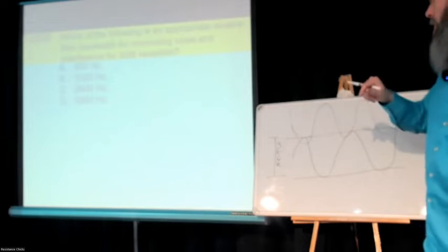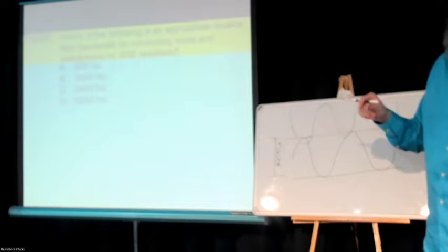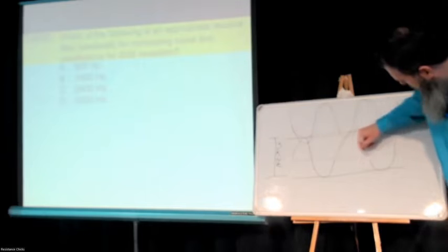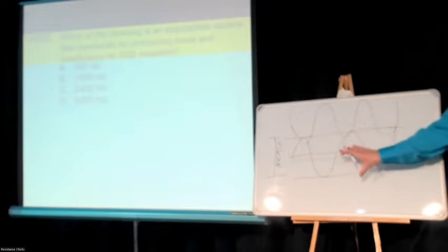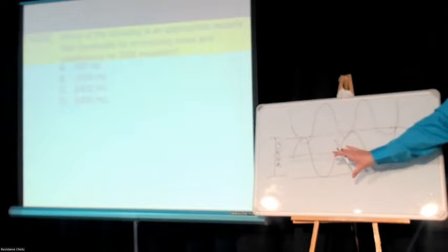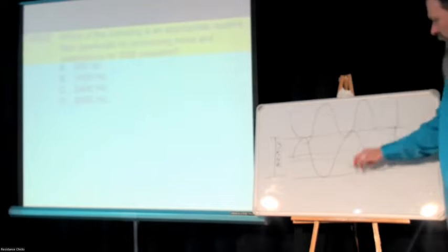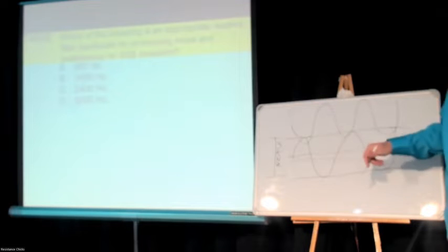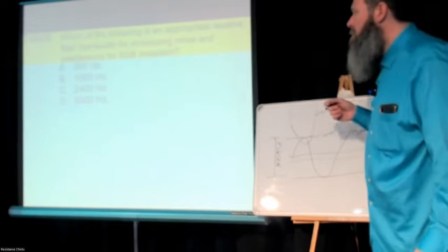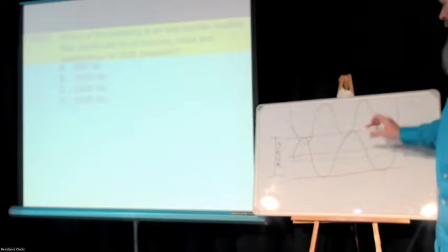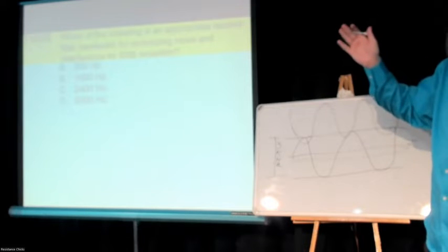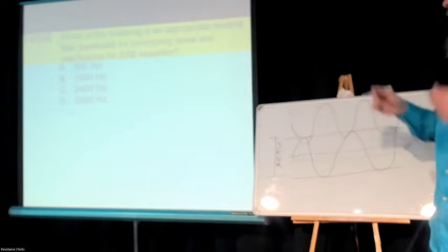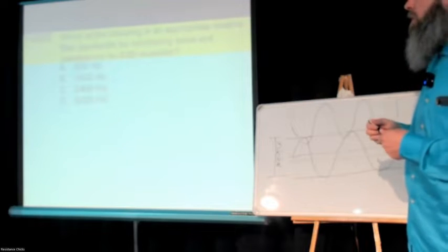Well, 500 hertz would be really tiny. That would be like only listening to this amount in here. You would lose a ton of signal. You wouldn't hardly hear it at all because you're missing everything else that's outside of this filter. 1,000 hertz. Okay, that's better. That's doubled that, but still quite small because we have a 3,000 hertz signal, right? 3 kilohertz is 3,000 hertz.